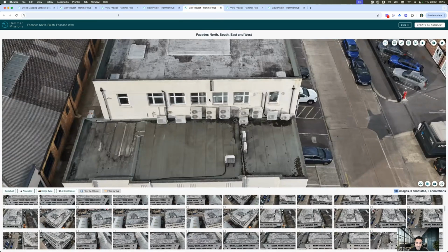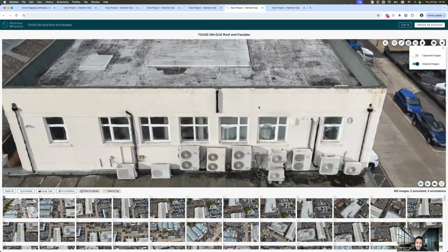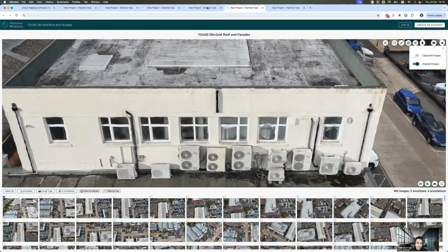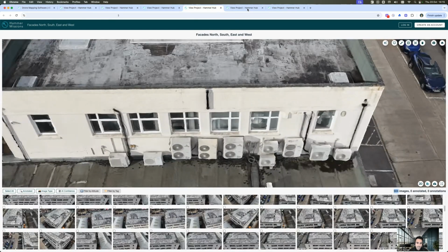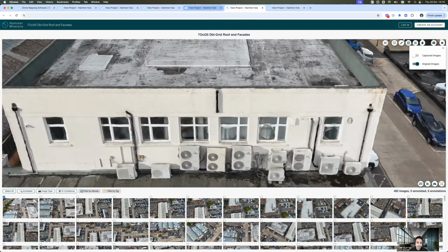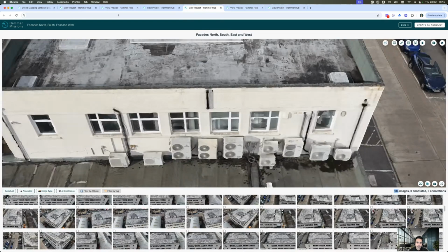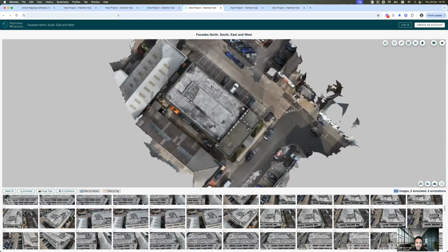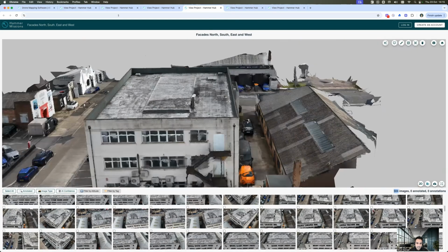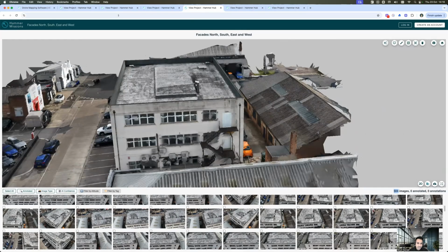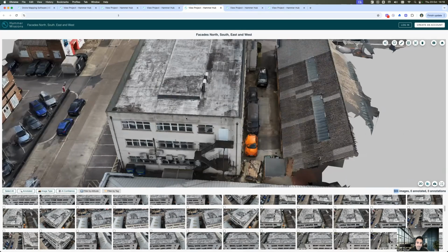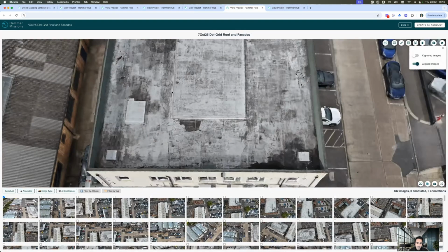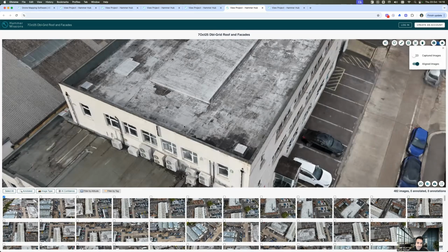And this is the previous flight plan where we were just flying the facades, and the facades look pretty equivalent, I would say, with slight improvement when it comes to both the double grid flight plan and the facade mapped together. However, the bigger improvement is actually with the overall model. So if we look at this overall model, and go to different segments of it, we will find that the facade on the other side, or the crispiness of the shape of the entire structure, is actually slightly better with the 2D grid map alongside the facades.